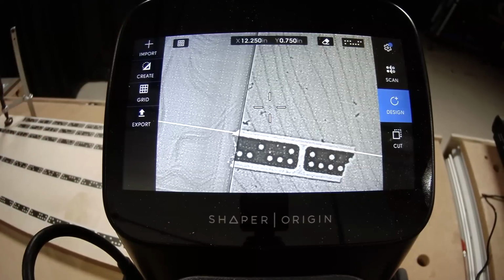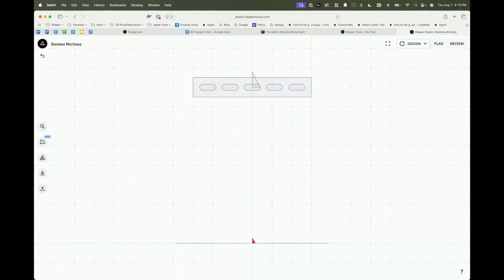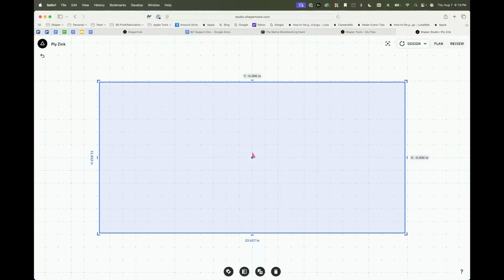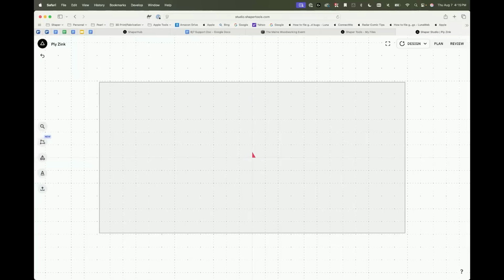Okay. Cool. So now we're going to go to Studio, and first thing, I'm just going to reload the Studio page. Since this is the last exported design, it's going to show up here, and you'll see we have a rectangle that represents the probed rectangle along with a center point and the custom anchor in the middle. Now, up in the Design tab, you'll see this little element here that says Add Origin Anchor. If you click and unclick that, it'll disappear and appear. You're going to want to make sure it's clicked when you want to export it back so that everything links back to that original location.